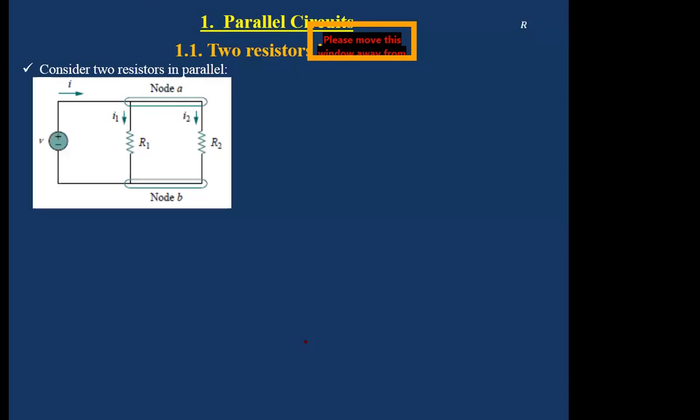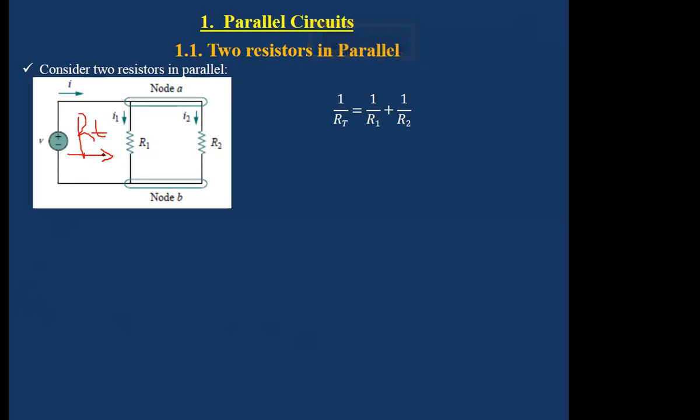So for two resistors now, in parallel, let's say resistor R1 and R2, RT will be the resistance observed from this side. So RT now, we will say 1 over RT should be equal to 1 over R1 plus 1 over R2. Then if you put them under the common denominator, primary school mathematics, you are now saying 1 over RT is equal to R2 plus R1 over R2 R1. And making RT the subject, you realize that RT is equal to R1 R2 over R1 plus R2.